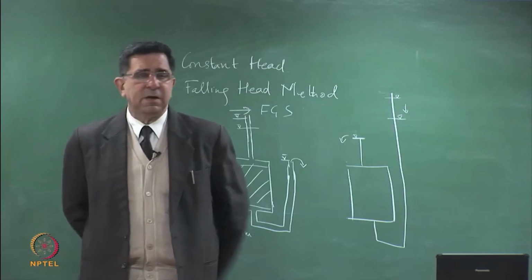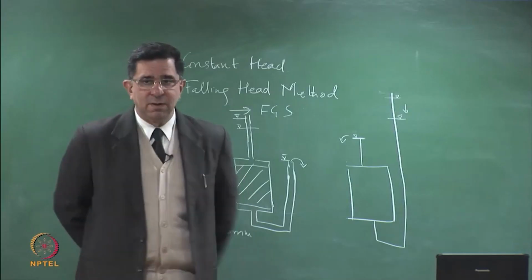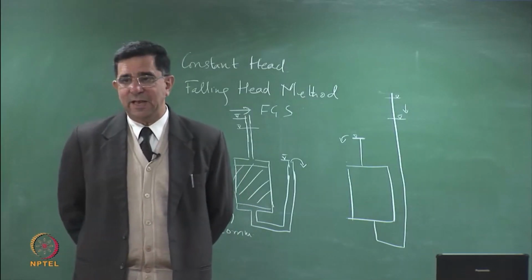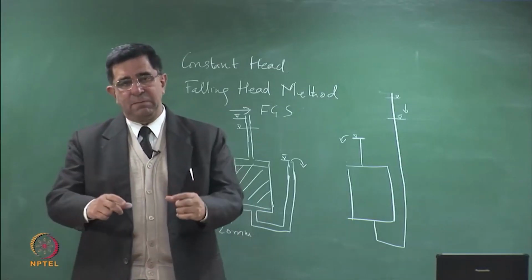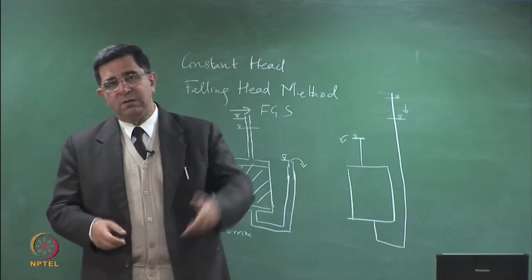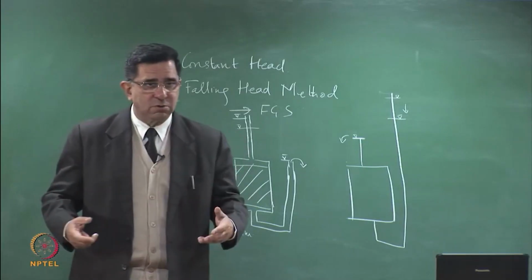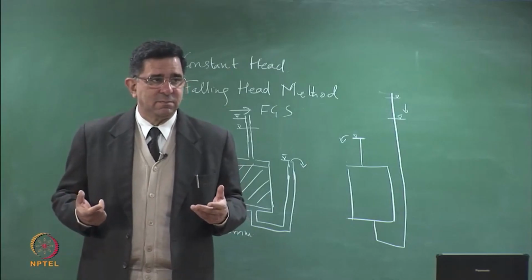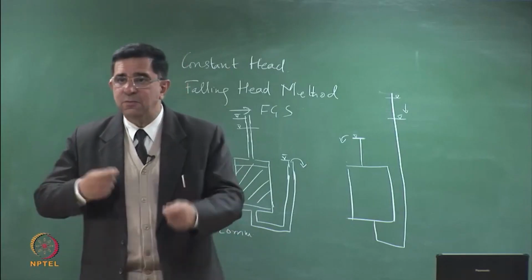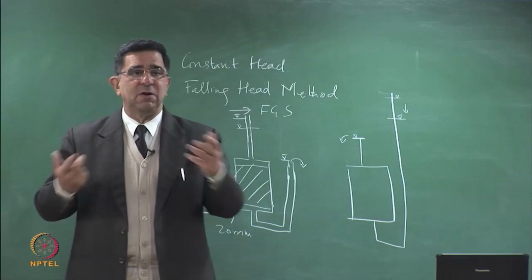Anybody would like to say? Typically we say soak the sample, and soaking the sample might saturate it, but that's a misnomer. Once you immerse a sample in water, the water is at the top also and at the bottom also. The air inside cannot come out unless it is being forced under some gradient to come out. Air will not come out.